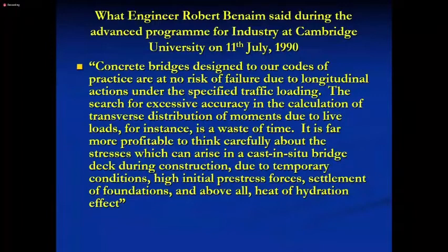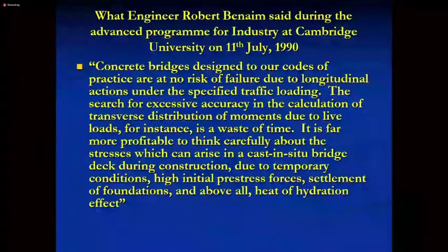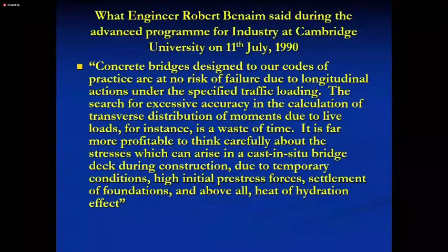Yes, just read what he said. Concrete bridges designed to our codes of practice are at no risk of failure due to longitudinal actions under the specified traffic load. The search for excessive accuracy in the calculation of transverse distribution of moments due to live loads, for instance, is a waste of time. It's far more profitable to think carefully about stresses that can arise in the cast in situ bridge deck during construction due to temperature conditions, high initial pre-stress forces, settlement of foundations, and above all, heat of hydration.